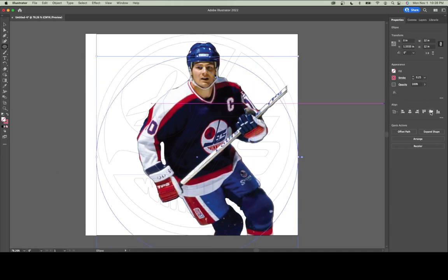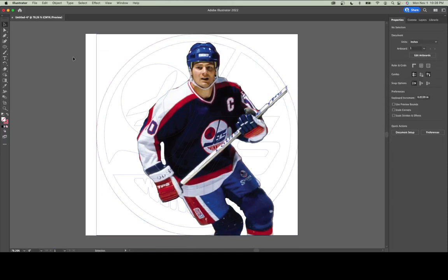And this is going to be important when I take this over to the laser because I want that shape that I'm cutting out to be a different color than the design that I'm just vector marking in. So it's going to vector mark or just slightly burn in the lines of the blue Jets logo here. And then I'm going to use the laser to cut out the red circle so that I have my sign fitting into all of this 12 by 12 circle with all the details revealed.